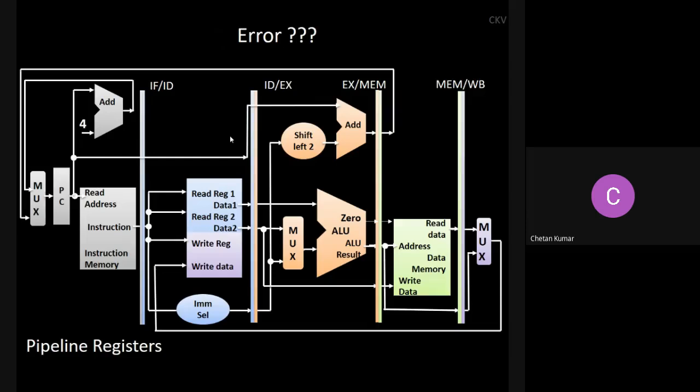The PC generation also is not a problem here. That's not a big issue, and again, that's not an error. So PC generation will happen normally. For normal instructions, you are going by this path. Only for branch instructions, where your branch condition is getting decided, you are taking this path. Or if you are implementing branch prediction, then you can move this whole thing inside the instruction fetch also. That is an implementation point.